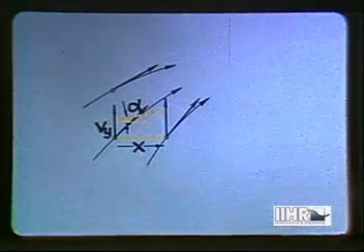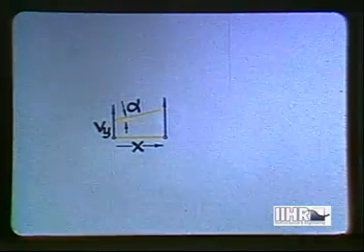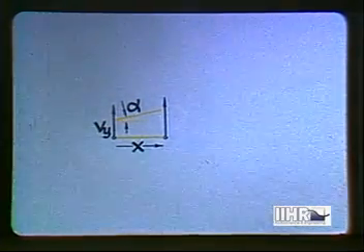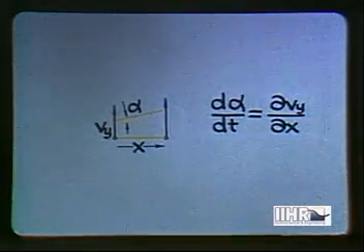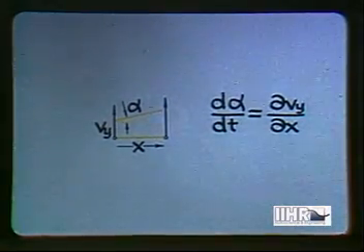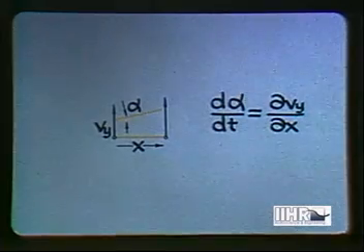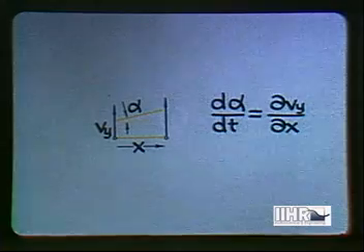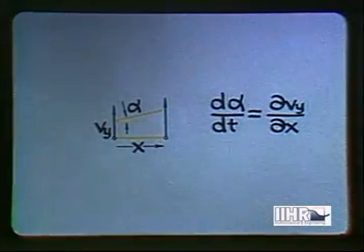In general, vorticity is not restricted to isolated filaments, but varies according to the velocity distribution throughout the moving fluid. It is then necessary to define it mathematically in terms of the velocity gradient. If the component of the velocity vector in one direction varies with distance in a normal direction, then the two ends of a line or a floating matchstick, normal to the velocity components, will move at different linear speeds, and the line or stick will tend to rotate with an angular speed equal to the velocity gradient.